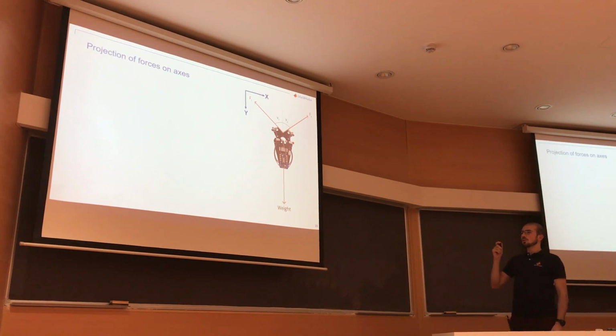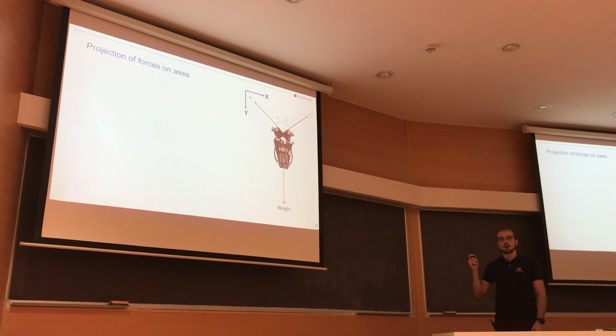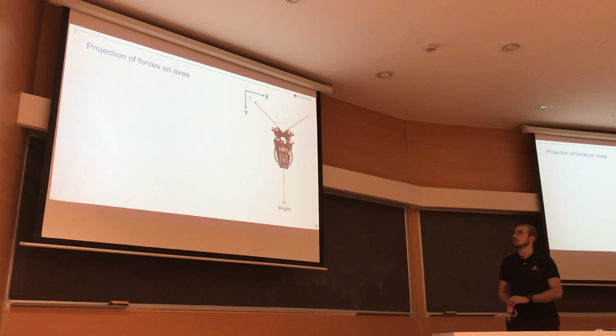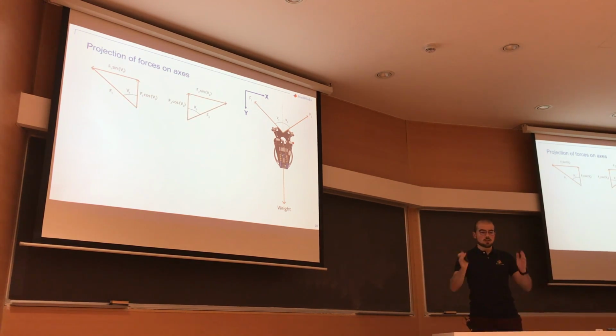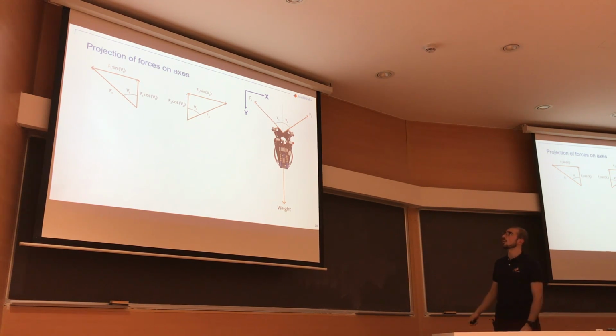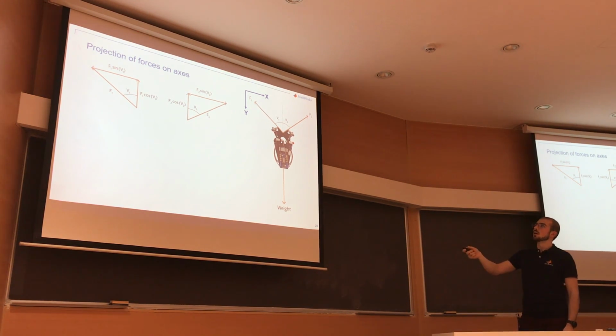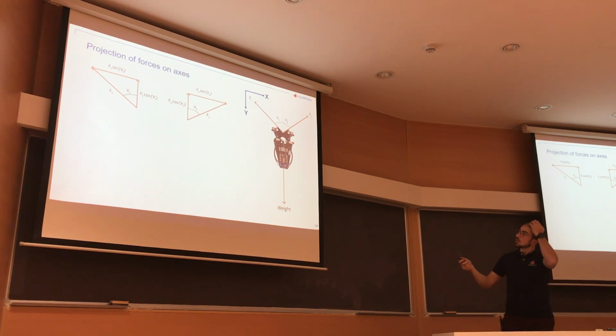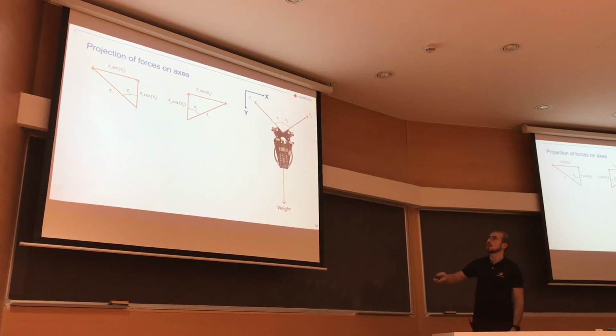Now, from the kinematic part, you have to remember that we define this as the reference coordinate plane. Okay, so we can decompose these two vectors, F1 and F2, using the projection law into the two components, F1 sine of theta 1 and then F1 cosine and so on.